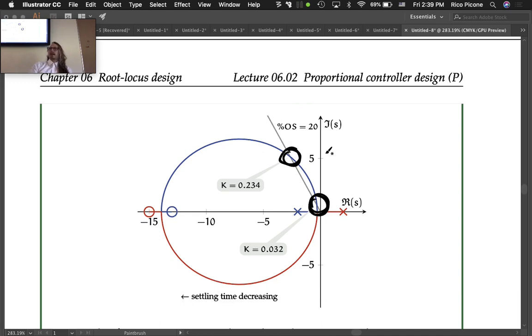So nothing stopping you. Step info is nice in that regard. You can just use it to go through the loop automatically. Yeah, feel free to do it. I think you only need precision up to the level of accuracy of your model. A lot of times our models are going to be a few percent off. So getting to one millionth in your design based on the simulation may or may not be of added value to you, depending on the system. Some systems are very well modeled, and it's a very complex system, and you're going to want a very accurate choice. But a lot of times, the gain choice that you make is only going to really be important within like 1% or 2%.